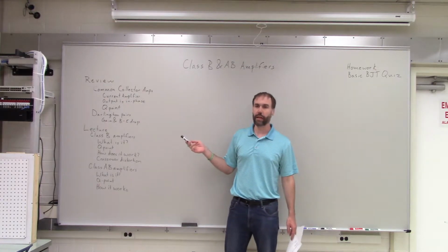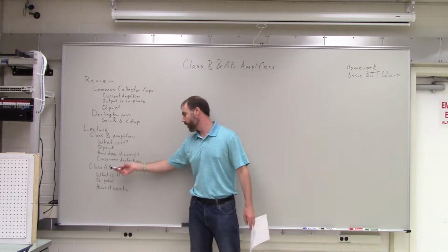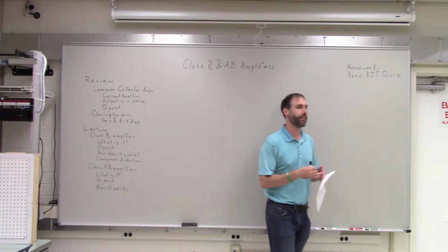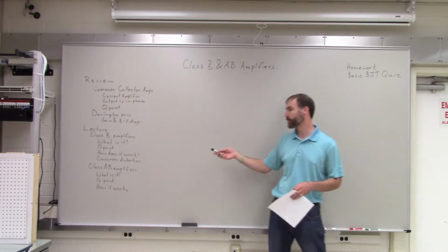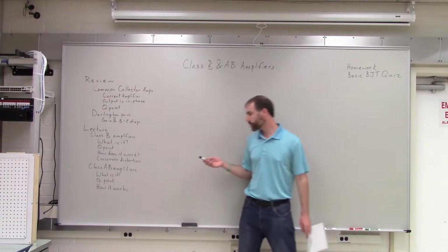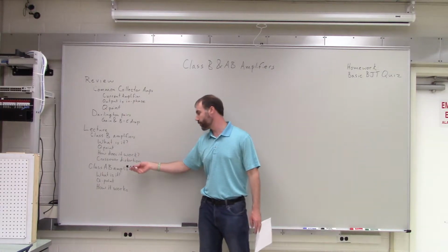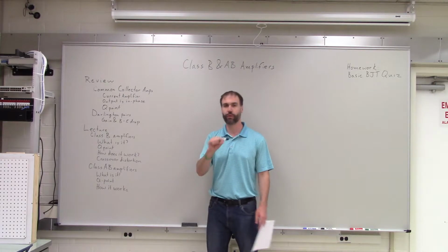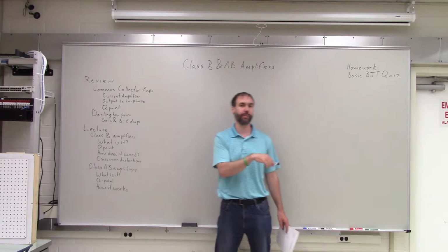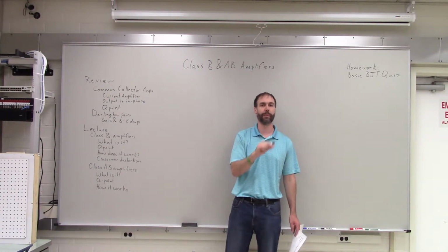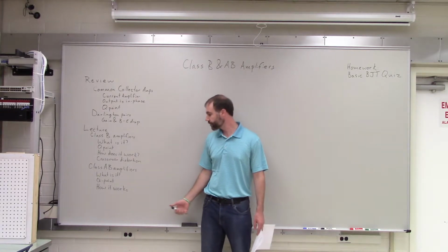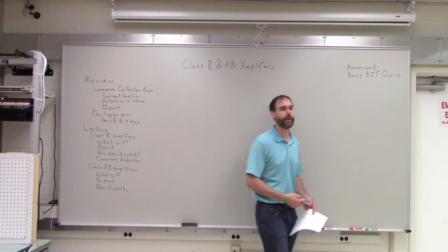So we'll look at Class AB amplifiers. These are a type of amplifier that try to get the best of both worlds. They want to have the nice reproduction of Class A amplifiers with the higher efficiency of Class B amplifiers. So they're trying to get that efficiency while eliminating that crossover distortion. And we'll see how they do that. And we'll see that the Q point is close to the bottom right-hand corner. It's just a little bit up. So it's using very little current when there's no signal coming in. Okay? So any questions about that before we get started?